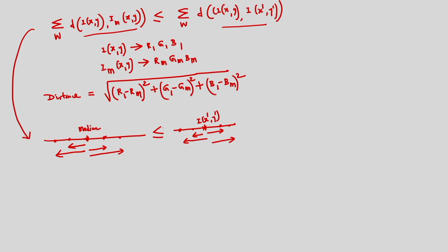Now, how to calculate the vector median? For calculating the vector median, I can consider one window, maybe a symmetric window, a 3 by 3 window. Suppose I am considering a 3 by 3 window.